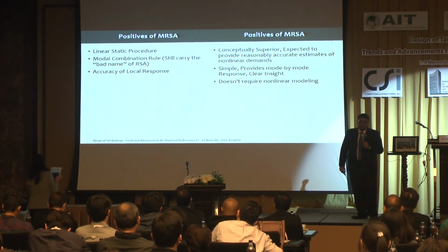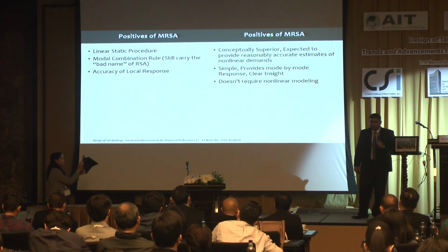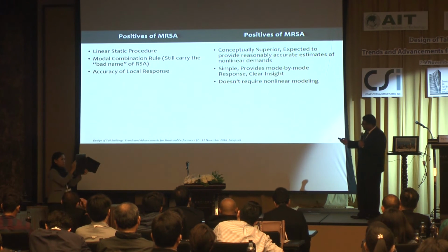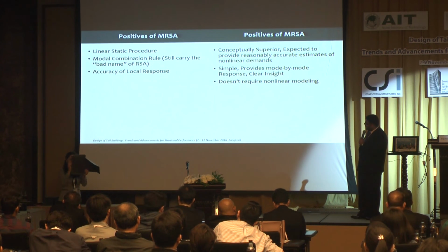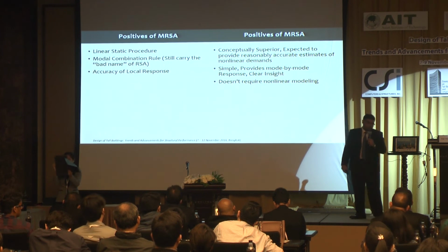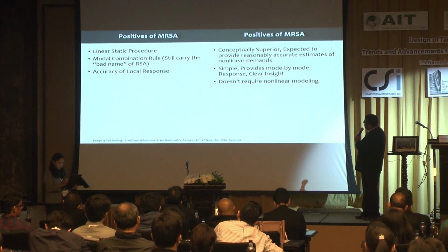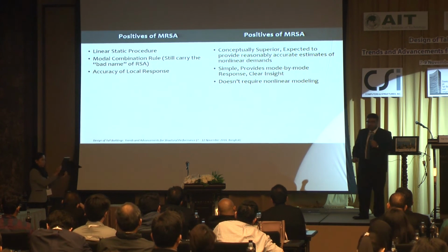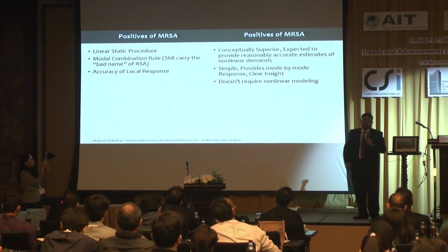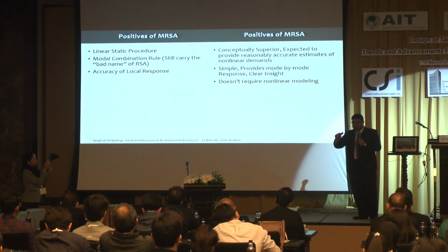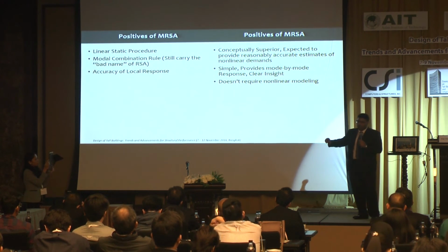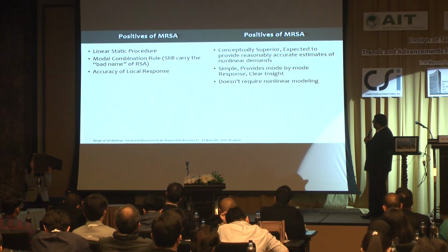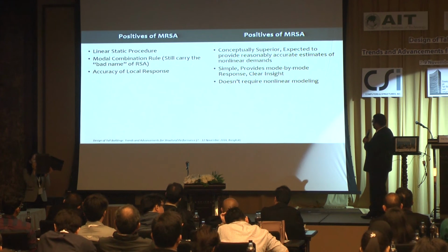Modal combination rule is still a challenge. People argue that SRSS is not an accurate modal combination rule, and this limitation is still there with our MRSA, and accuracy of local response is also an issue. But positives are that it is conceptually superior. It is based on more understanding, not just the direct scaling down of ground motion. It is based on the idea that each mode should be treated differently. So it is conceptually superior compared to the current prevailing code-based RSA, and it is simple, provides mode-by-mode response.